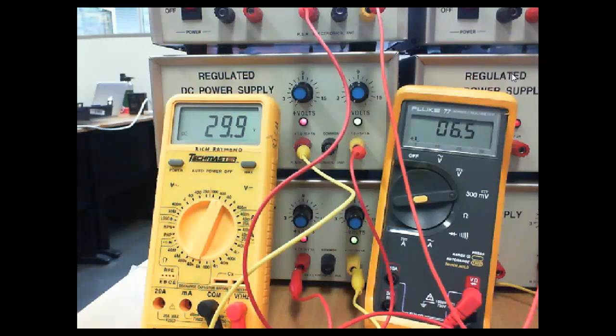So I come over here and I say, okay, 6.4 divided by 1 million. So I come up here and I've got 6.4 microamps. Is that what you got? So now I know every one of these answers are going to be in microamps. 6.4. So if I measure 10, that's going to be 10 microamps because we know that 1 meg ohm resistor. Is that what y'all got?